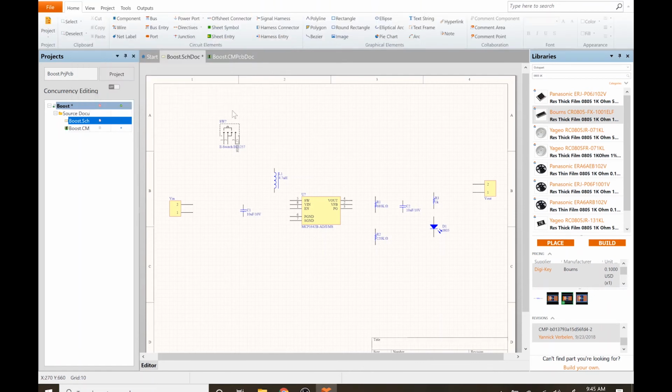All right, so the next step is to actually start connecting them all. You can bring up a wire one of a couple of ways. You can press the wire button up here, that brings up this little crosshatch, or you can press W, which is a shortcut for wires. And whenever you go over to a clickable part where it will connect, you can see how the inner X changes red and gets slightly larger. It's not as visible, but you can see it.